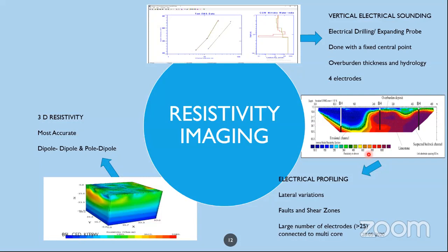To make it simple, the color blue is around 250 ohm meter. So wherever you see blue color, it indicates 250 ohm meter. 250 ohm meter can be any type of soil. It can be clay, it can be sand. You can see the depth here also, from ground surface to a depth of 38.7 meters. It will show roughly clay with a mix of sand.